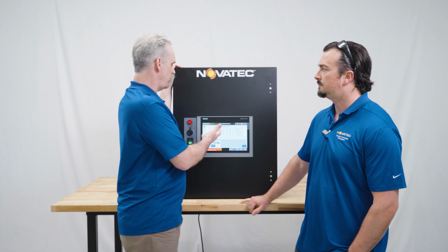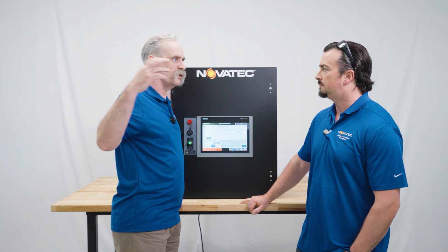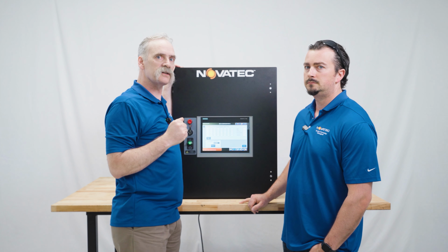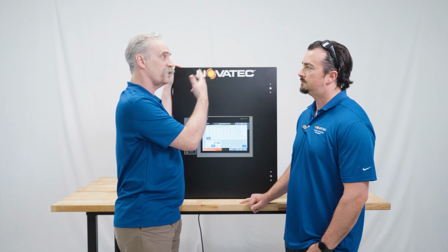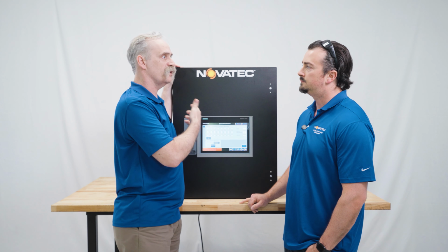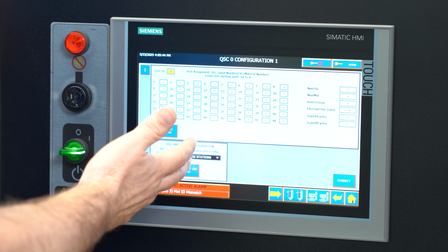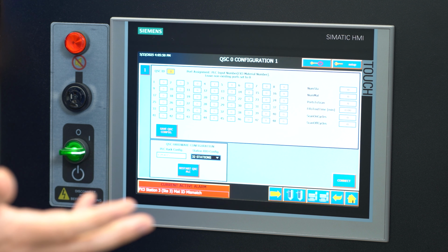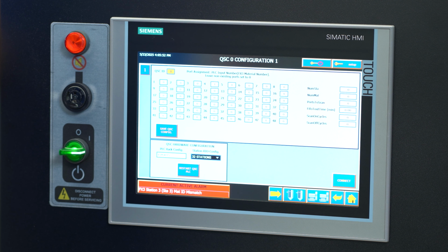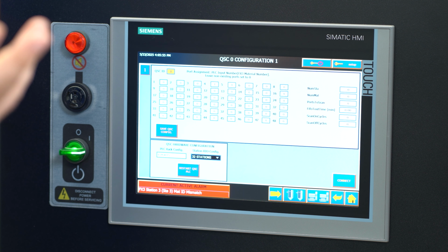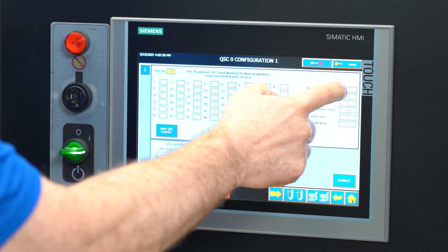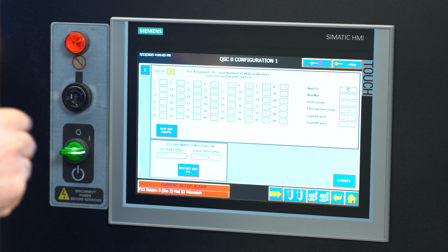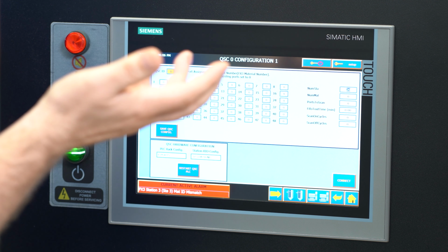it reboots, and now it's using that configuration and is looking for the remote I/O box that's typically up in the ceiling that is wired into the flex line hoses, and now it knows it's there, it talks to it and starts scanning and sending the outputs to pulse through. So we just set up the 32 stations for the remote I/O configuration, but if we're not using all 32 stations, and maybe we only have 20 machines that we're going to, we can actually limit the number of stations through this value, and we can limit it to the 20 stations for our pulsing side of the system.